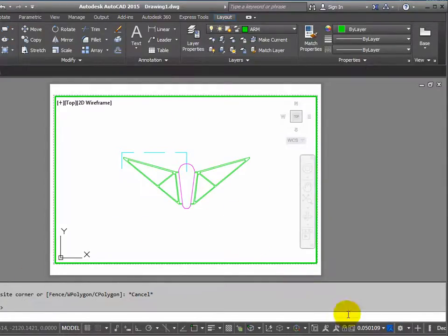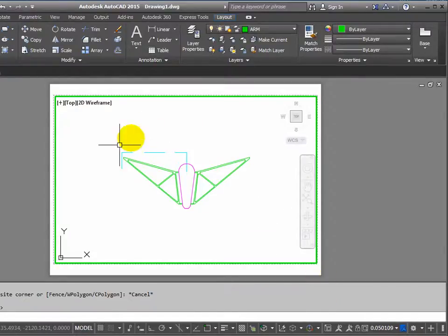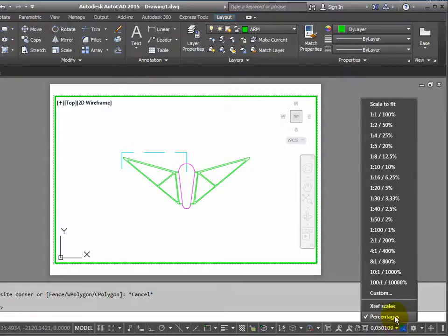Right, so we're missing a wee bit of what's happening over here, but it should be okay to see what's going on. This is what I was trying to reveal, this little feature here, and this is the zoom setting for that viewport. If I can get that to a nice round number, then we're looking more at an architectural or an engineering drawing scale. So let's see what's on the list. Okay, they're expressing them as kind of ratios and as percentages. 1 to 1 obviously being 100%.